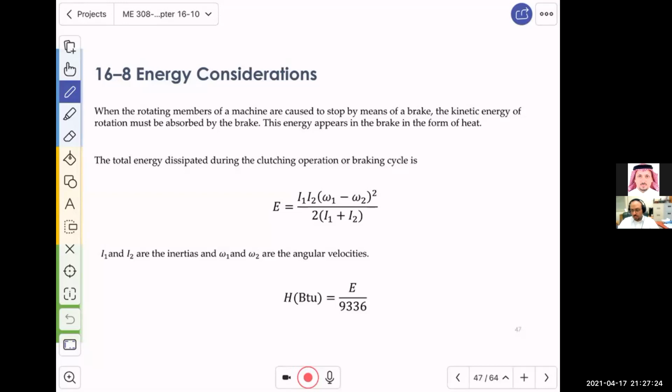And then we will basically take that energy, assuming that most of it will be converted into heat. Once that energy is converted into heat, we will be more interested in knowing what is going to be the temperature for the brake and/or the clutch, and would we have problems reaching a maximum temperature? Because as you might know, the material which we use as a bed for the frictional material, whether it is a metal base or a non-metal base, will always have a limiting maximum temperature.